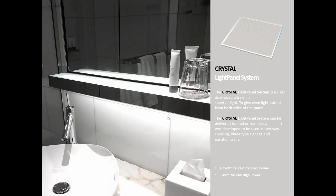So our crystal light panel is different from our basic or framed light panel because it eliminates the white reflective backer on the back. What this does is give us dual side illumination. We take the clear acrylic and laser etch that pattern onto both sides of the acrylic. So when the LEDs shine inward, it picks up on both sides. For shelving applications, you get illumination on the top as well as on the bottom.